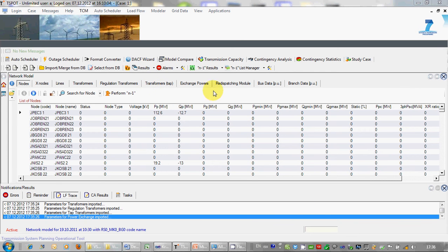This video presents a typical everyday use of the congestion forecasting tool for the power system load flow steady-state calculations, which could be used for the following purposes. Calculations of load flows, losses, complex voltages, and alarms on each branch and node of the power system. Studies on new generation connections.